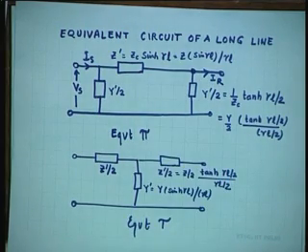There is a problem given in the book where I have asked you to show in tabular form the values of sending end quantities, power factors, currents, voltages for all the models: small line, medium line T, pi, long line exact, long line T, long line equivalent pi, and you compare how the values vary.